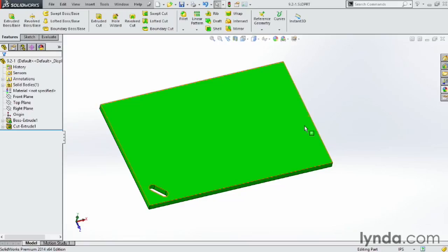However, if we like a grid pattern, like a set of holes or a vent, for instance, we might want to select a second direction. Directions are chosen by selecting any edge or line that goes in the direction we want the pattern to go in.